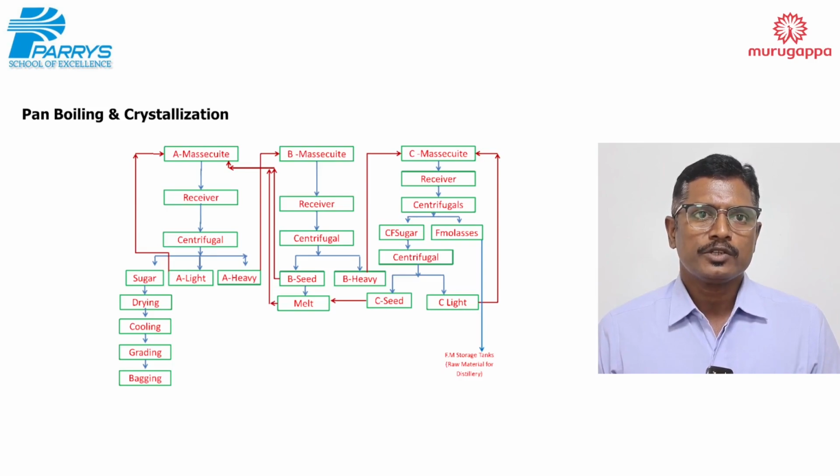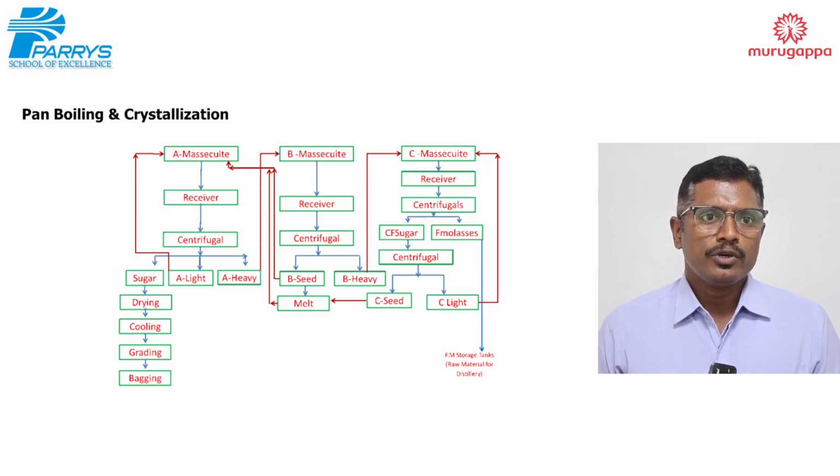The simple flow chart of pan boiling and crystallization: A massecuite, B massecuite and C massecuite. A massecuite goes to centrifugal, there we separate the sugar and the molasses. That molasses is separated in 2 parts, A light and A heavy. This A light and A heavy will be sent for reprocess. Sugar will be sent for drying, cooling, grading and bagging.